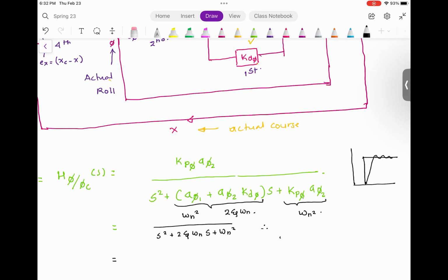And what you should see is, your aircraft should be able to hold level flight for a long time. It may go up, but at the end, let me see. Okay, it's an Aerosonde parameter. So what you would notice is that the aircraft should be able to maintain level flight for some time. And in the Aerosonde frame, if you look at it, its CG is located up front. So by design, it's stable.